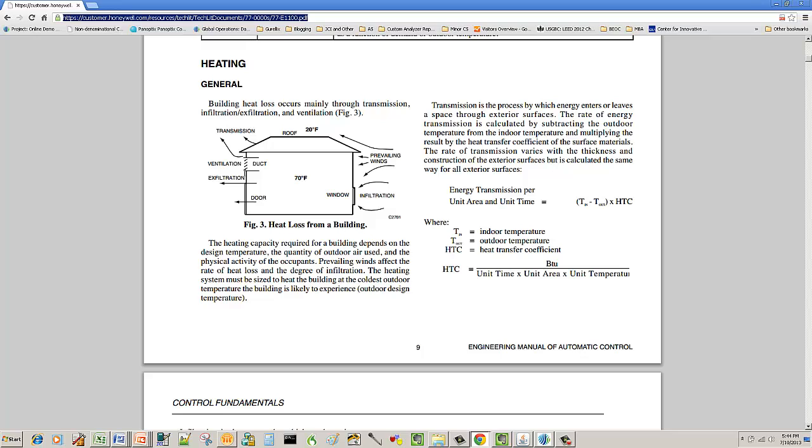We talk about two concepts that are pretty important here, and that's infiltration and exfiltration. Typically a building ideally is wanted to be positive. What does that mean? That means that air is not coming in, rather air is going out. So if you were to open a door, you'd want to feel a slight breeze leaving the building. What does that do when a building's positive? Well, that's going to keep thermal infiltration, ideally from these winds that we're seeing, from different outside pressures, from coming into the building.